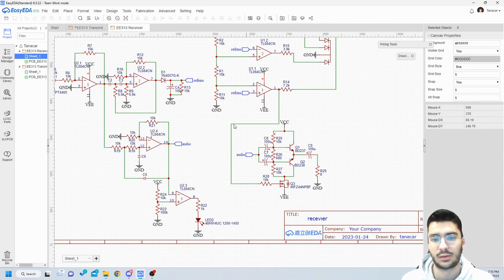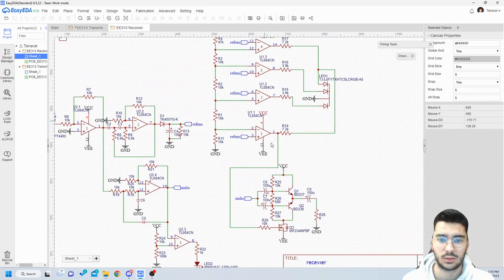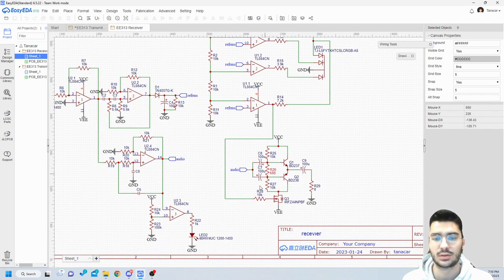And then we have our driver circuit. Finally, the driver circuit has an on-off switch MOSFET, which is controlled by the reference RMS level logic. If the reference signal is below a threshold, then this circuit is cut off. It's not on. If there is an audio signal, it would not generate any current from the speaker. But if we are above a certain threshold, then this circuit operates.